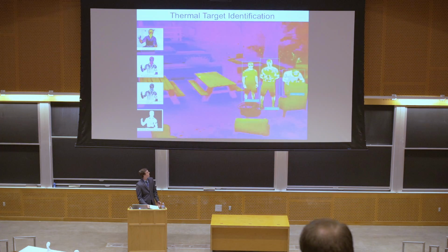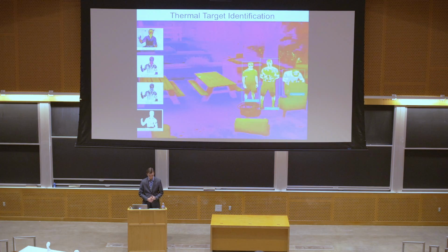In addition to this, the UAS is equipped with a 640 by 512 long-wave infrared imaging camera that is incredibly sensitive. This imagery, an image off of the camera shown here, is the starting point for our algorithm, and it provides the basis for what we begin working with. First, the live feed is taken and thresholded to the human temperature range, and then this new image is converted to grayscale and Gaussian blurred to remove some of the noise, as well as get us ready for further image processing.